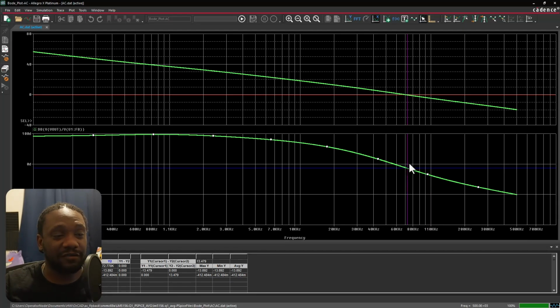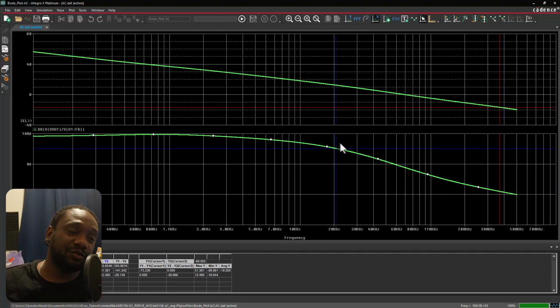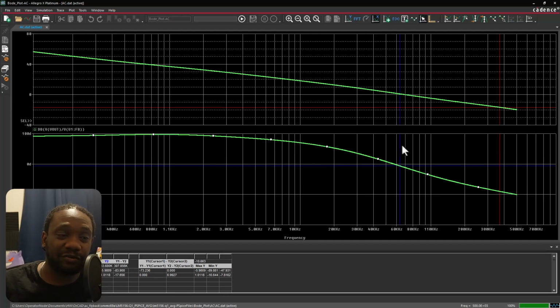Once we know we're far enough away from that, then we have a lot of margin, a lot of space where we can get that boost in gain all the way down to minus 16 dB, and we're still fine in terms of loop stability. Now, if our 0 dB crossover was really close to 180 degrees, then we would have a problem. By really close, I mean anything less than 30 degrees. So if you're down to like 150 degrees by that crossover frequency, you could be cooked.